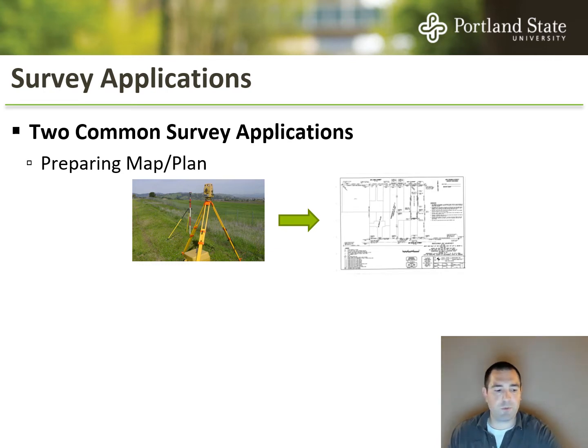Oftentimes nowadays that would be a total station, sometimes with GPS and robotics to help streamline that effort. They'd go out, they'd measure elevations, features like where's the storm sewer, property lines, things like that. If there are monuments out there, they'd collect all of that data, they'd bring it back to their office, and then they would prepare a map, an exhibit that shows all of that data that they collected. That's what most people think about for surveying.